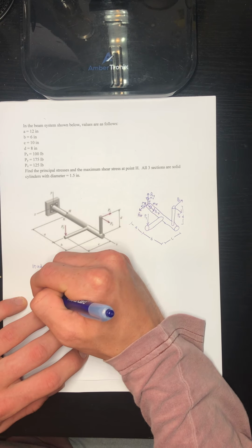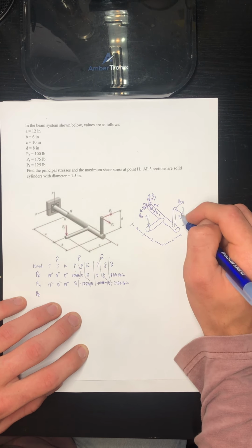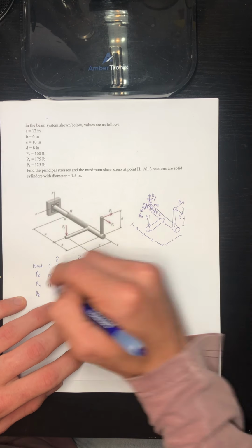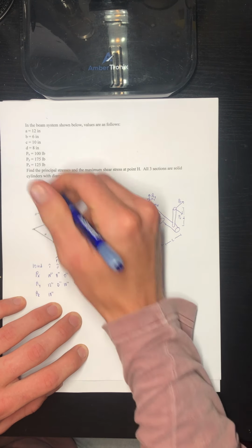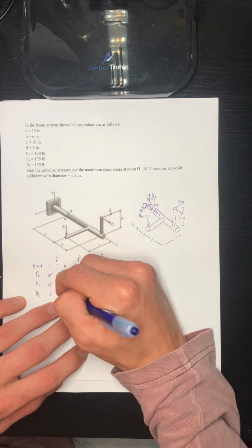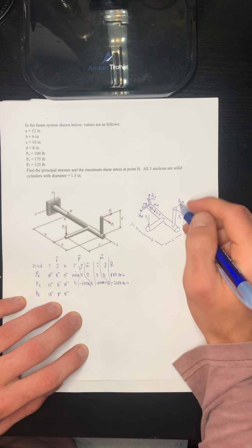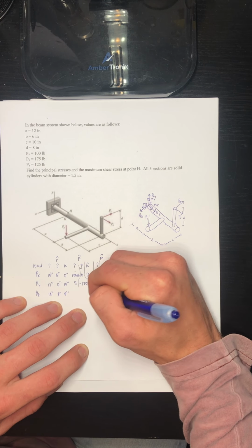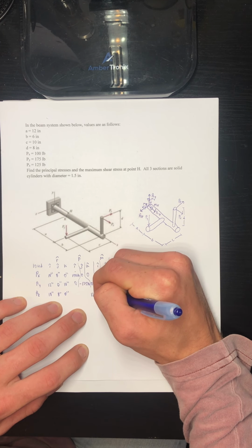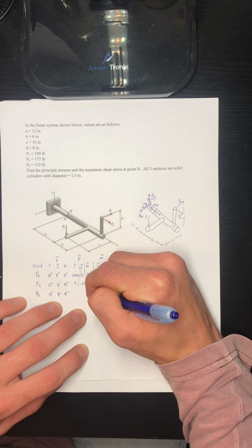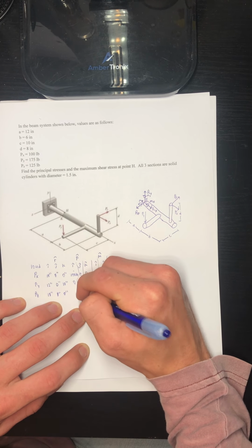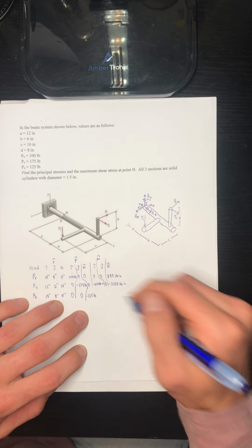We have our load being applied at Z, also up here on this pillar. It is 18 inches out in the X direction. Matter of fact, just the same as the one up there as the PX. So let's go ahead and do this. The load's only being applied in the Z direction. So we have PZ is equal to negative 125 pounds. And 0 in the X and the Y direction.